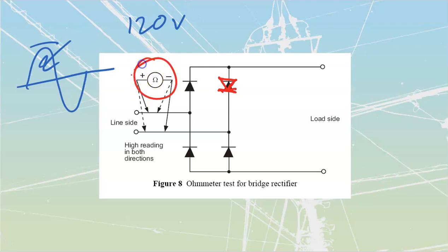What's going to happen is my ohm meter puts out a small value of voltage. That's how an ohm meter reads. It puts out a small value of voltage that it knows about, and then it reads the amount of current that goes through the circuit, and then it does the math inside of its little ohm meter brain that says, I put out this many volts, I had this many amps flowing back through it, therefore the resistance that I'm going to display for this electrician here is going to be this many ohms. It's doing that all inside of itself, but it means it does have a positive and a negative. That's coming off the battery that's inside of your ohm meter.